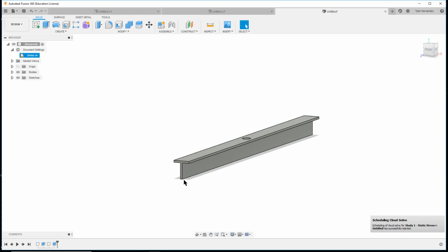And what that means is, even though maybe this last inch or so is going to be sitting on a table, when these ends bend up, it's only going to be touching the table at one point, somewhere in from the end, right at the edge of the table. And that's all we need to model here. So I just need to add a tiny point right here and a tiny point right here where it's in contact. It doesn't need to be contacting the whole surface.